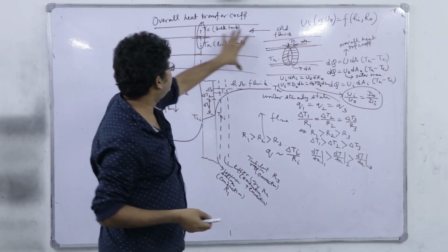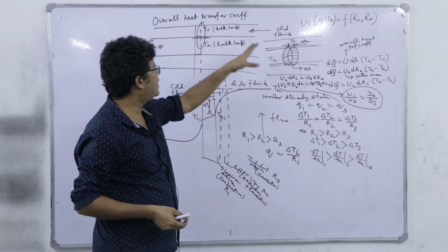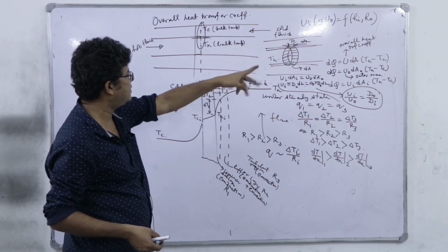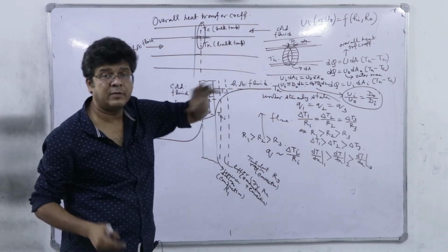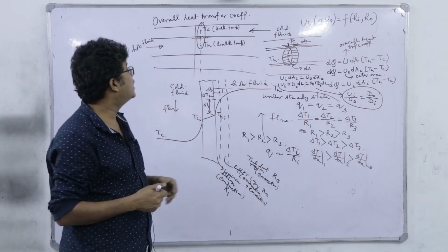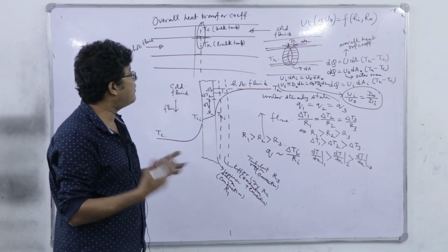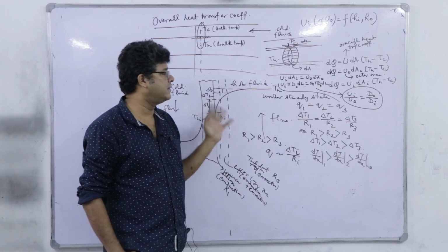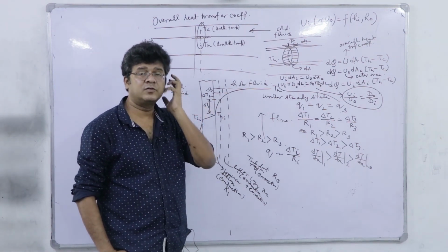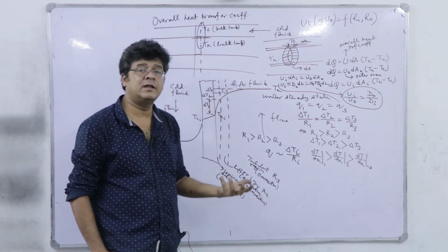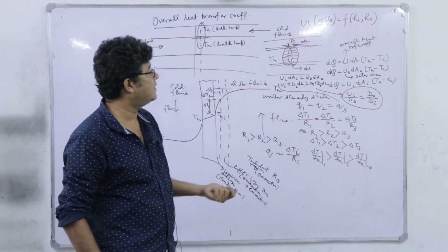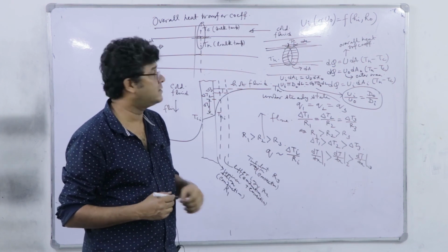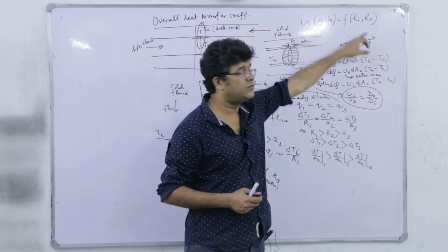And as the temperature changes, this temperature difference, what I have written as Th minus Tc, these Th and Tc are progressively changing. So there must be some average temperature difference, and everyone knows that it is the logarithmic mean temperature difference. So why we get it, and what is the mathematical analysis by which we get this Q is equal to U A LMTD, that we are going to discuss in the next session in addition to this functional relation. Thank you.